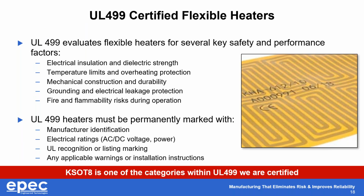Once UL 499 testing is completed, each heater is then allowed to be permanently marked with the manufacturer's identification number. That's that E 6-digit number I mentioned previously. The heater must be marked with its electrical ratings, not just the voltage, but whether it's AC or DC.